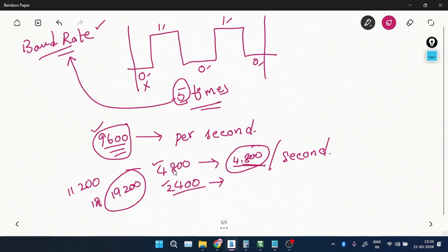The interesting fact here is, in order to establish this baud rate, you have to go back to timers. So again, you have to know the basic timer calculations, that is the timer frequency, then timer tick period, then counts, and then preload value.